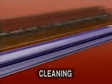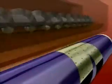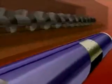In the cleaning process, the toner remaining on the drum is scraped off by the main blade and captured by the recovery blade. The collected toner is then stored in a separate compartment from the unused toner in the toner cartridge.